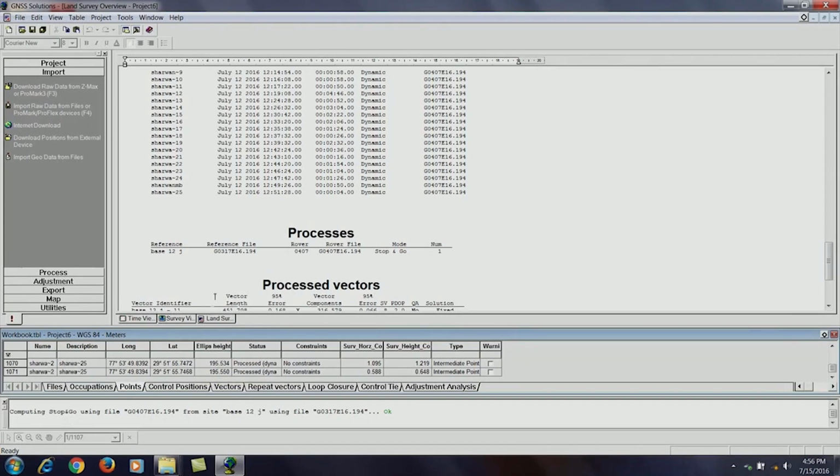In that way we can go for GPS surveying to establish the point location of point objects and points along the lines showing the roads, corner of the roads or the boundaries, and joining them we can get the linear objects or areal objects.